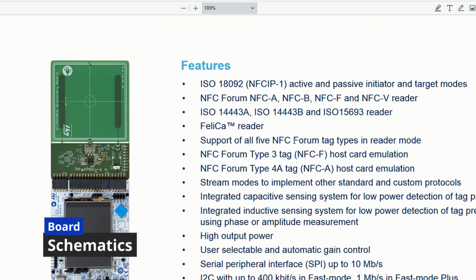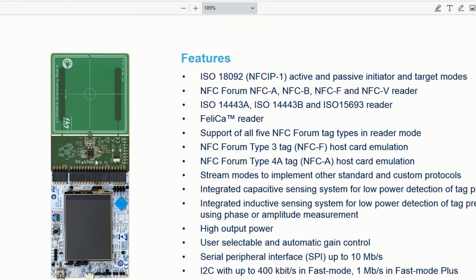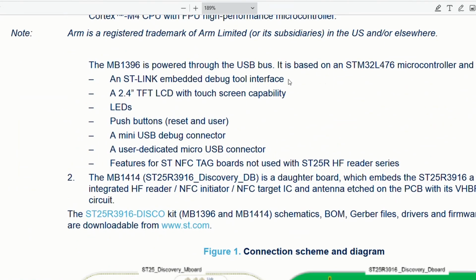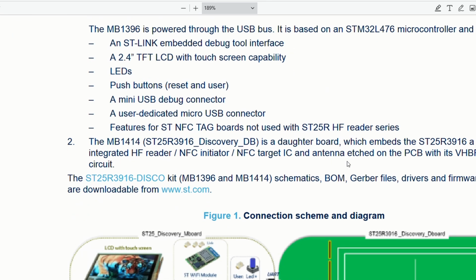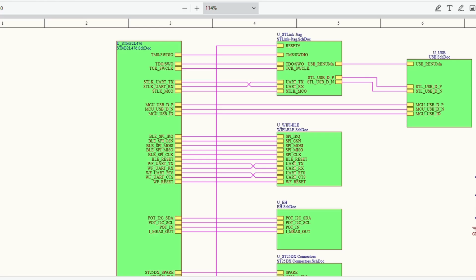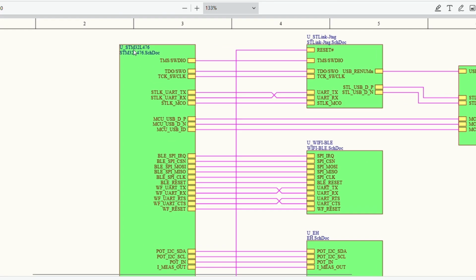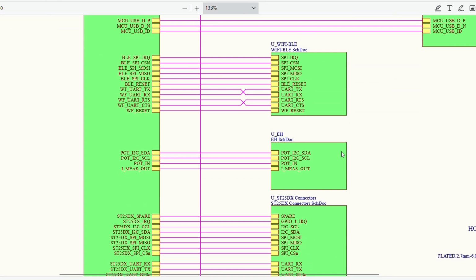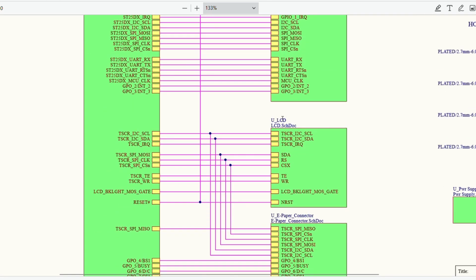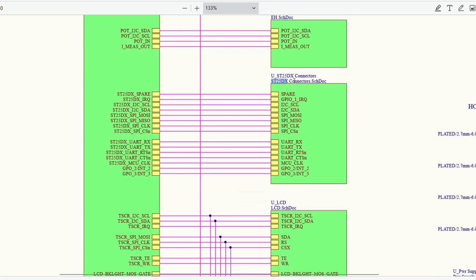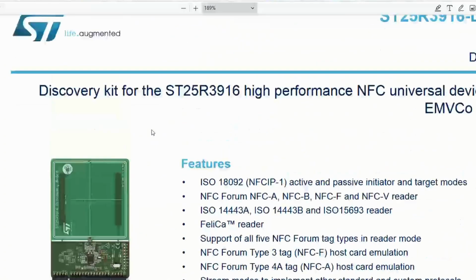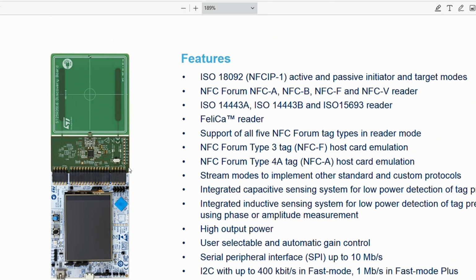Let us now talk about our STM32 board. So the reference ID of this particular Devkit we have is ST25R3916 Disco. And this is basically for RFID and NFC based applications. The green bottom part is the RF antenna and RF chip, while the top part has an STM32L4 based chip and TFT display. So I thought to use the top part with the TFT display to give us a better visual output of our GPS data.